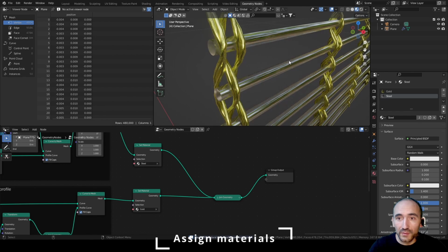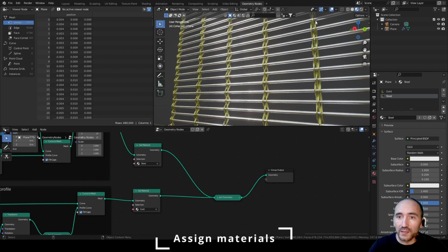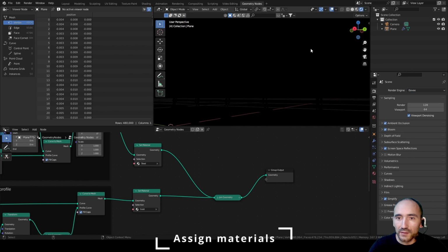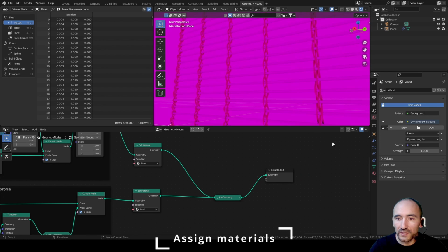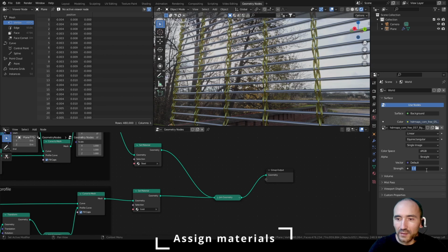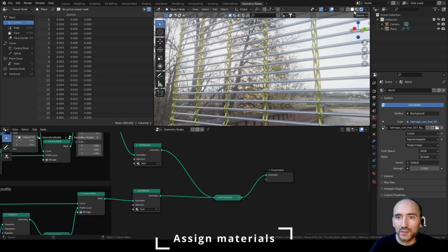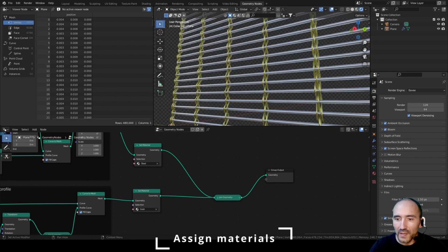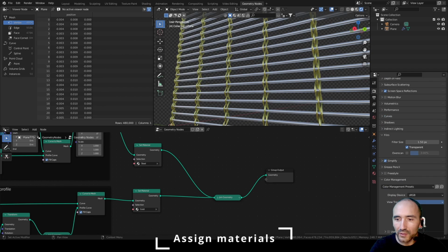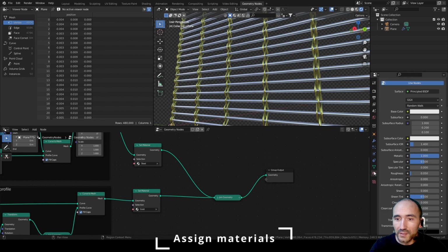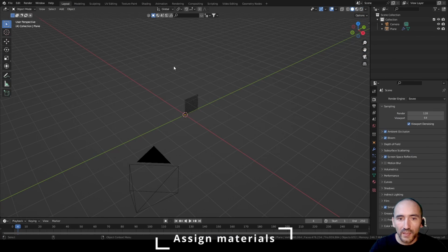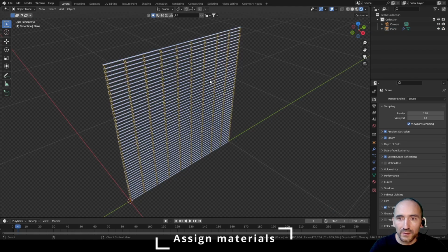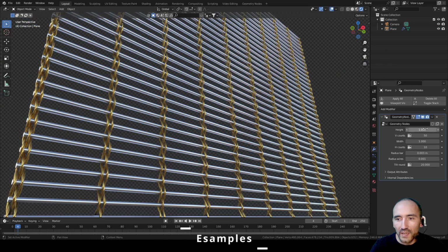Go into the geometry nodes, in the material preview, and we can go here, select EV, select the result here, go to the environment, select color, environment texture, open and select your source image of the HDR, set a strength you want, go in the render properties, under film, make it transparent, color management, not filmic but standard for this tutorial. Let's tweak the material of the gold, more orange, and in layout, select focus, select the rendering value, and you can make it as you want.